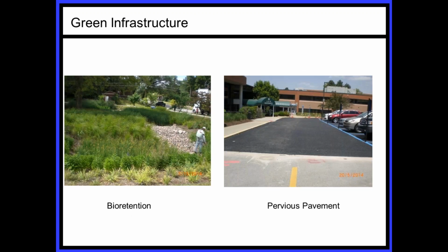So stepping back a little bit to redefine again, one of the primary methods utilized for green infrastructure is bioretention. There are, again, plants, swales, etc., that use native vegetation, usually with very deep root systems, usually native plants to that area. The other is pervious pavement. Again, there are 3 main areas there. This picture happens to be asphalt. The other 2 main ones are concrete as well as pavers. The idea with these is to capture the water in that surface or over that surface and take it down underground and give it time to control the flow.